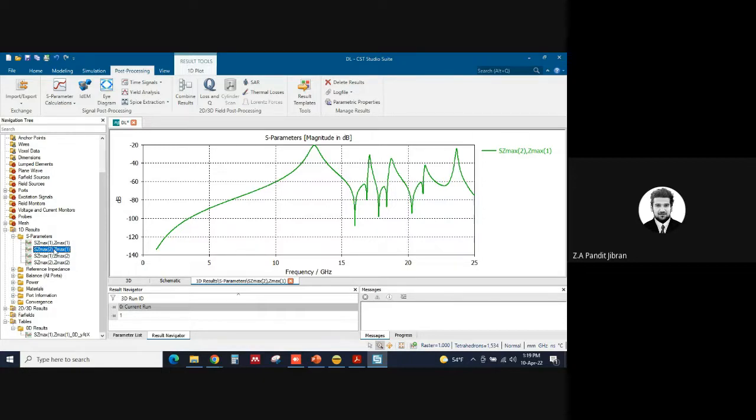Is there any option to enhance the beam forming on this metasurface? Definitely, there are a lot of papers. What you have to do is control the phase. That's it. It is a kind of phased array, but with spatial feeding instead of direct feeding. Your patch is radiating, and you control the radiation pattern in such a way that the phase is compensated.